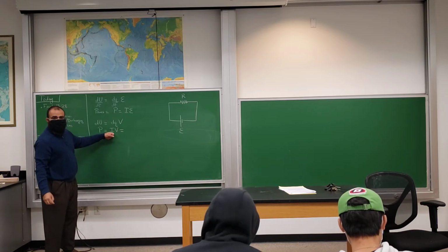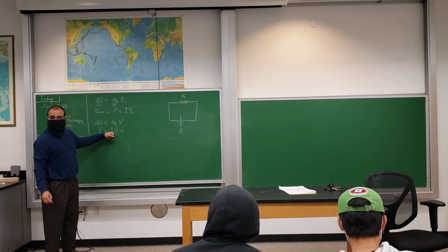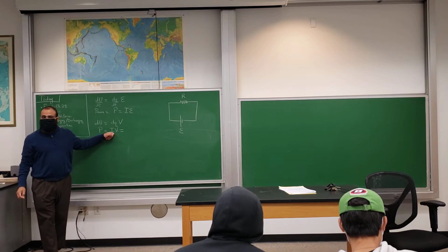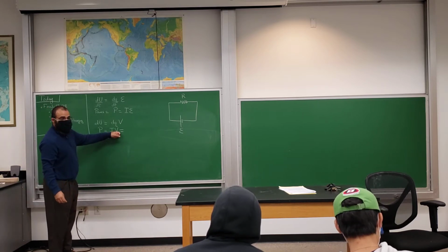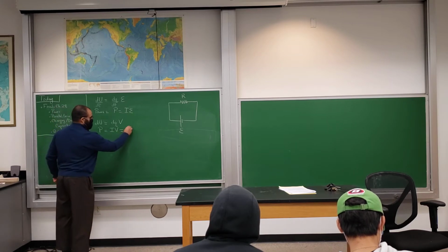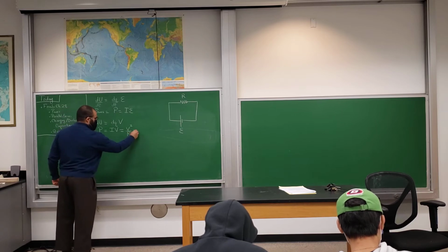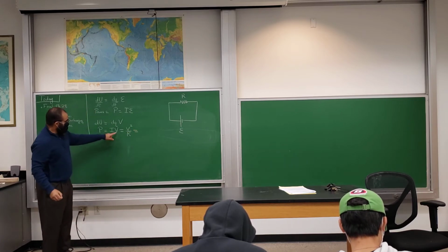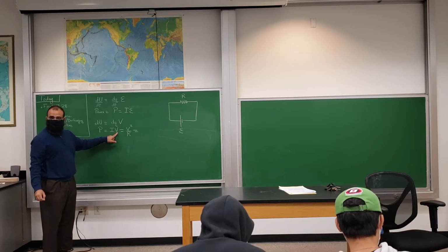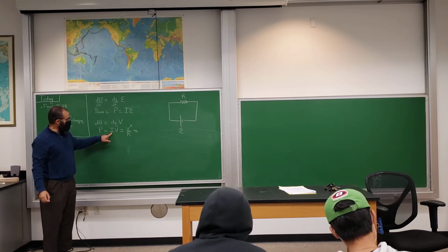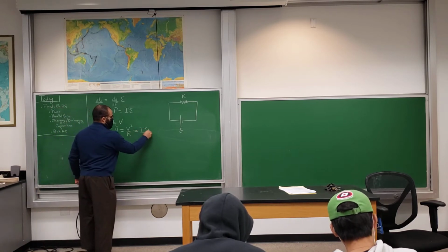The current is V over R, right? The current in a resistor is the voltage across the resistor divided by R. Which law is that? Ohm's law, yeah. So it's V over R. So if I have here V over R times V, what do I get? V squared over R, yes, over R. And another one that you sometimes see, V is IR, right? V is IR, according to Ohm's law. So you have I times IR, so you get I squared R. I squared times R.